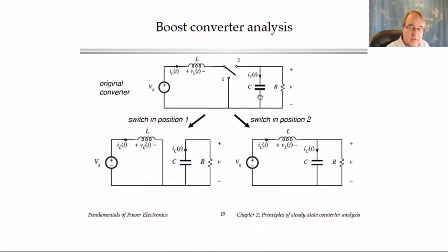I've defined the inductor voltage and arbitrarily chosen its reference direction as plus on the left and minus on the right, which means that if the variable vL(t) is positive, the voltage is in the direction shown, and if vL(t) is a negative number, then the actual voltage will have the other polarity.